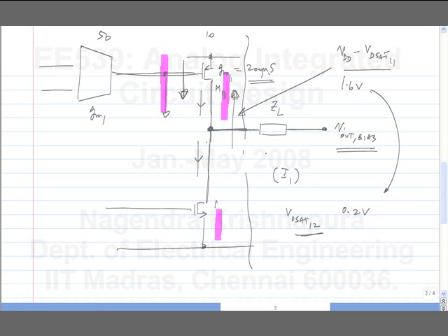So this corresponds to a 1.4 volt peak to peak sine wave, right? This is the largest sinusoid that can be accommodated. Now if you pass this through a 5 kilo ohm resistor, what is the maximum current that needs to be pushed or pulled?